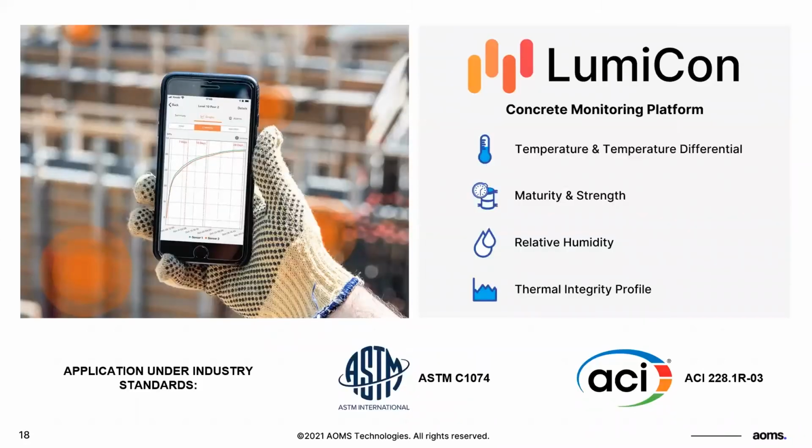Now, speaking about the technologies out there, LumiCon is one of the technologies that can be used for all different types of concrete pours and concrete placement, from a quality perspective. We all know that concrete sensors are also important to make sure that the concrete does not overheat. I mean, the temperature differential between the core and surface doesn't go beyond 19 degrees C or 35 degrees Fahrenheit. You also want to make sure that the differential between the surface temperature of your concrete and the ambient temperature is not beyond like 15, 20 degrees C, within that range.